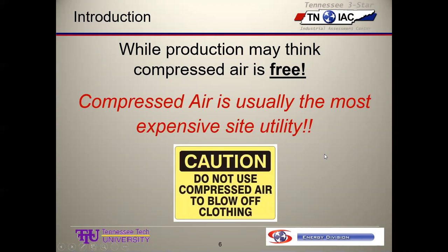Okay, so if you've worked or co-oped or interned in a production facility, you realize that the people out there making stuff on the line, doing maintenance, etc., consider compressed air to be free because they don't have to pay the utility bill. But compressed air is usually the most expensive site utility of the common ones. You may have something special at a particular plant, which may be more expensive. But generally speaking, compressed air is pretty expensive as an energy source.